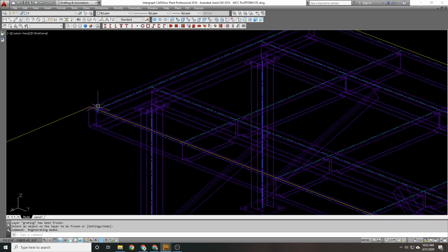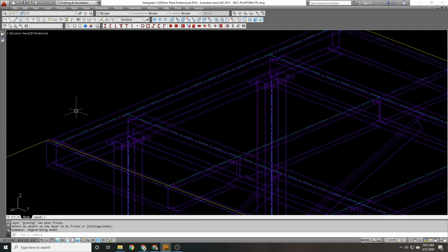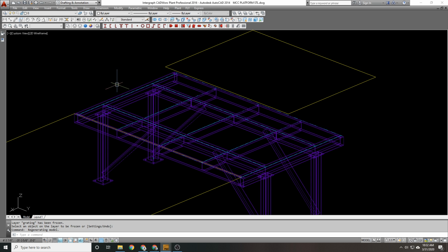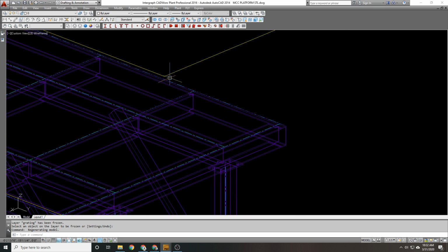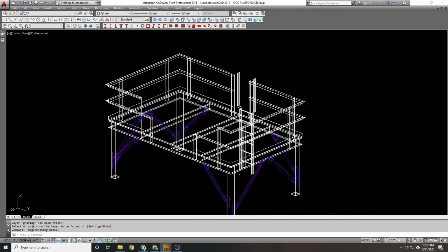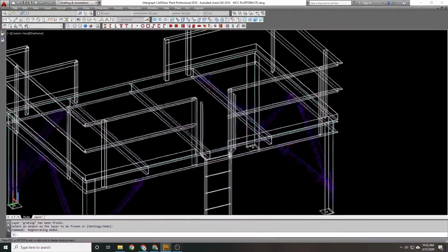But the thing about the handrail tools, it always wants to put pieces at the very ends, and you likely won't have posts at the very end. What you're going to have are, for example, this corner. If I use the handrail tool on this corner, it's going to want to put a post on the corner. That will never happen. You'll never have a post on the corner. You're going to have a post just before the corner. Now in this particular case, I'm using angle piping, and it is angle handrail, and it is going to have to go on the sides.